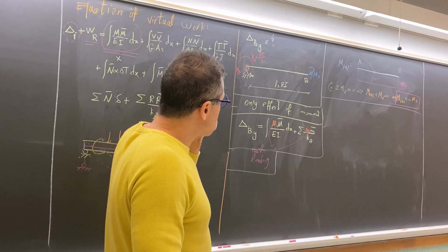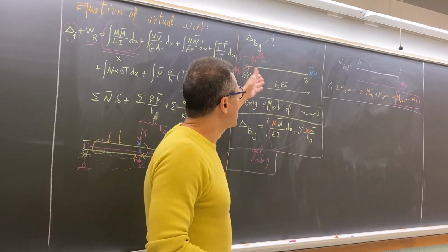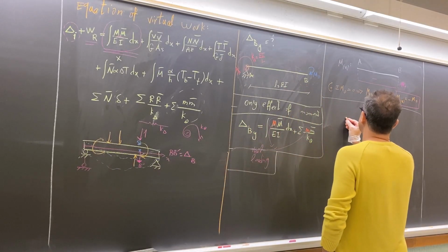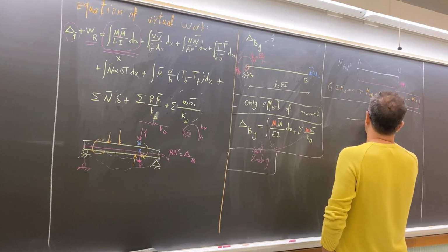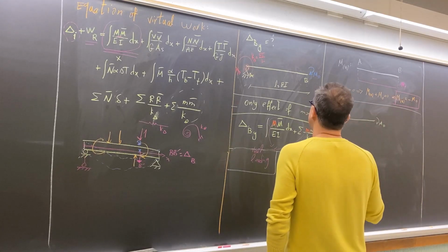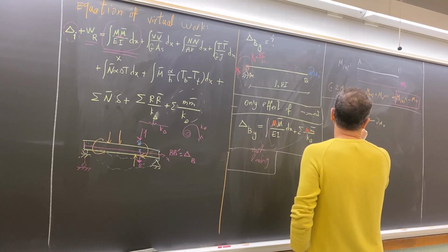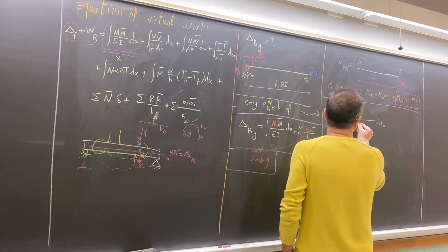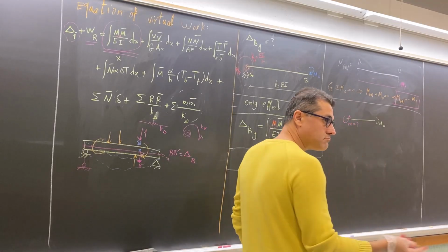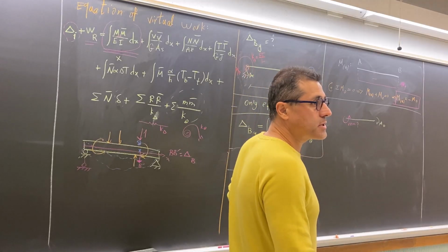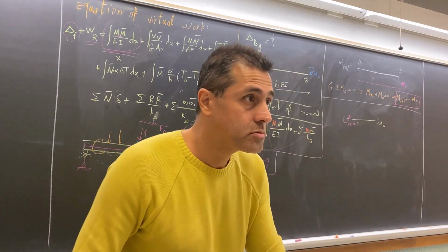Or you can just draw the free body diagram and write the equation. So let's go to the statics systematic method. This is M0. And then for the torsional spring, I show it with M, and M is unknown. M is the amount of moment inside the torsional spring. I give you time to digest it.